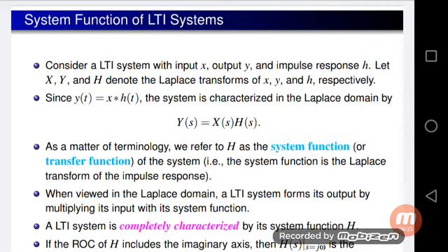When viewed in the Laplace domain, an LTI system forms its output by multiplying the input with its system function. That means when calculating the output of an LTI system, we use the system input and the system function H of s. An LTI system is completely characterized by its system function H.